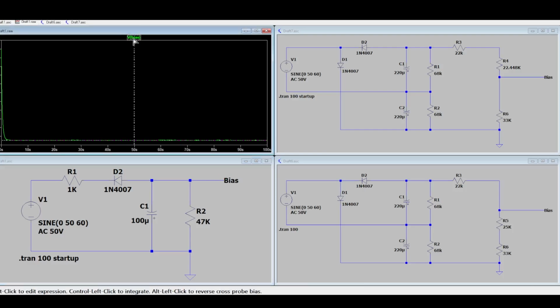But we can also click here and see, okay, we go from 0 volts, it'll settle at negative 41.8 volts, which is pretty dang close to our schematic negative 38 volts, especially since this is unloaded, so it will be slightly higher than what will actually be in the circuit when this is connected to a load.